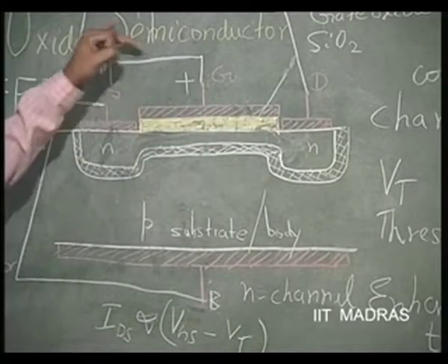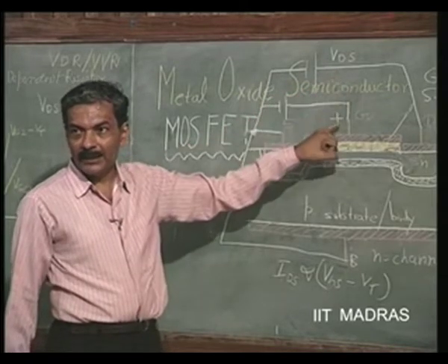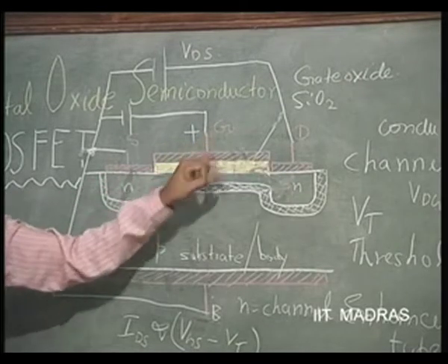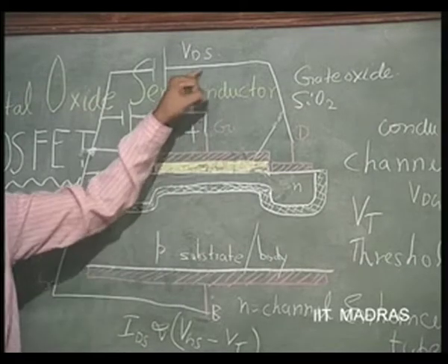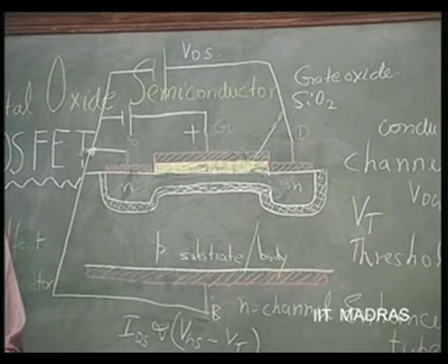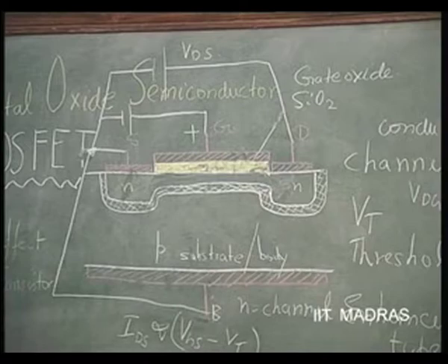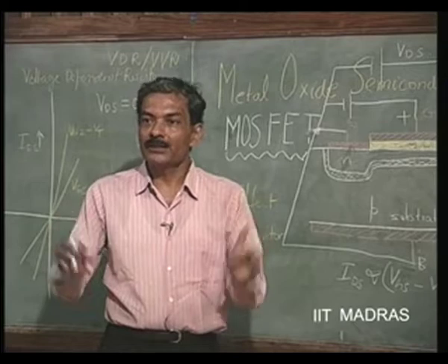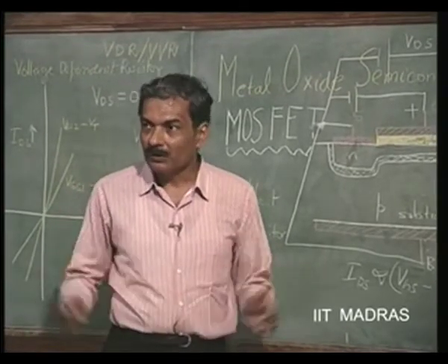That means the voltage that you apply here is of the same polarity as the voltage applied to the gate, so that the effective voltage between drain and gate will be opposing one another. So, the VDS that I have to apply here in order to close this channel at this point corresponds to VGS1 minus VT if it is VGS1, VGS2 minus VT if it is VGS2 that I have applied to the gate, and so on.